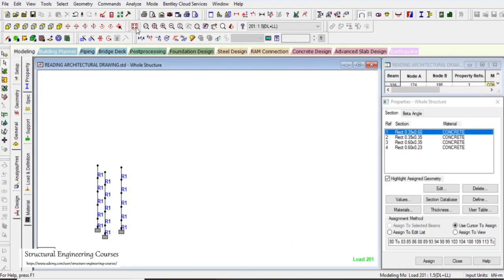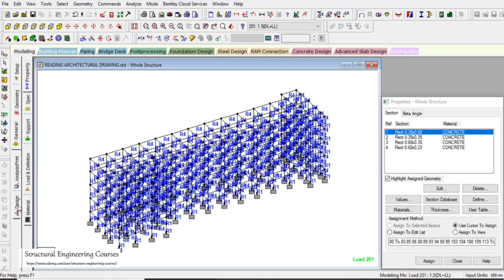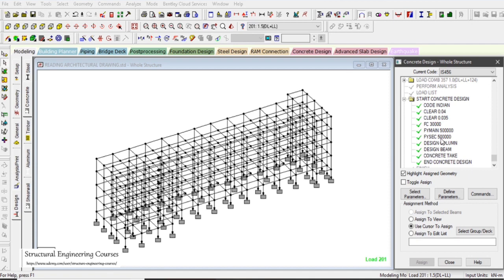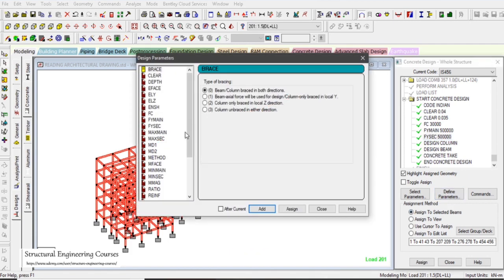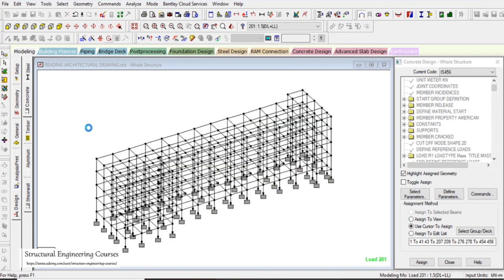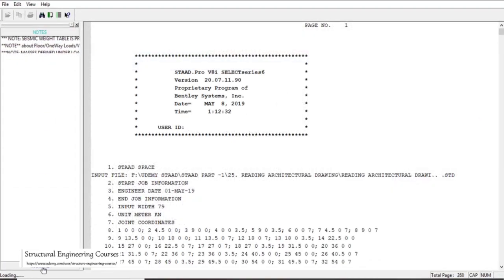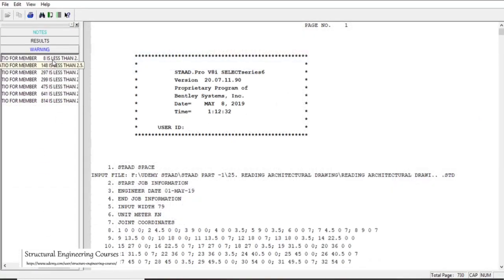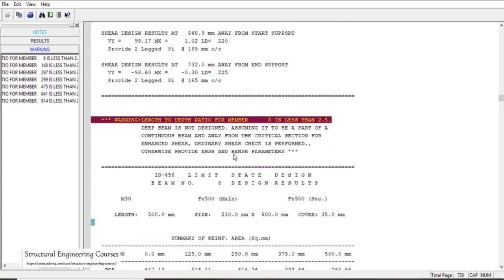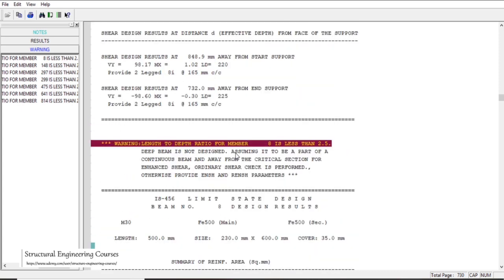And if you are very keen to remove these warnings also, then you can go to F5 sec here, and you can range parameters here. Let us say the range length is 0.5 here, so left click on add here.